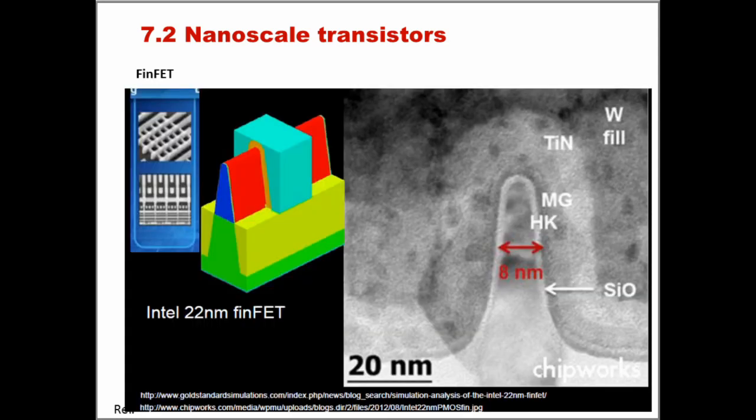And on this slide, you can actually appreciate a real FinFET. This is an Intel 22 nanometer technology FinFET. So it's extremely amazing what they managed to do there. And just please note how thin is the fin at the half height. And note also that in this particular device they are using a metallic gate.